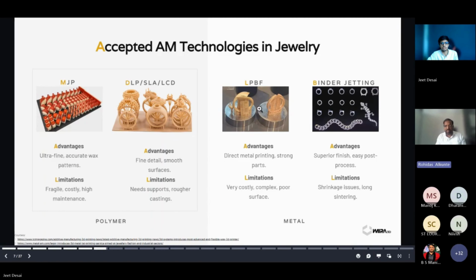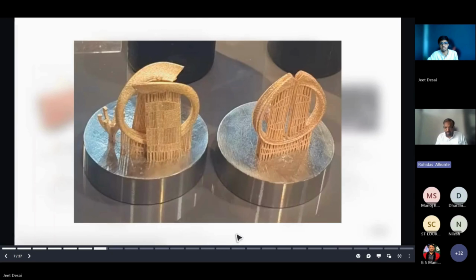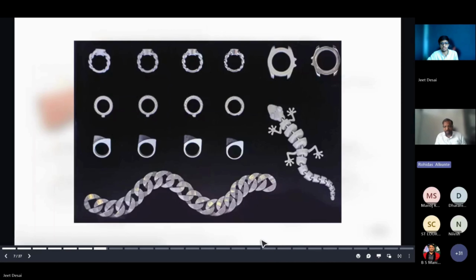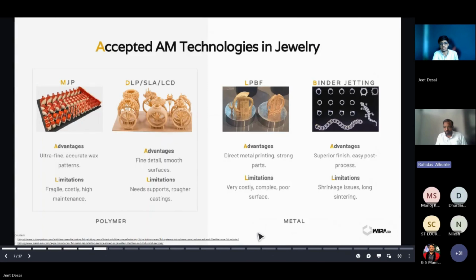And now the industry's approach is to print everything in direct gold. So people are exploring if it is possible to get it 3D printed. Now the challenge is to get a correct surface. If anybody can give this surface at say 2 or 3 micron Ra value, then no one can stop them from being a billionaire in this industry. So this is an opportunity you can think of, and if somebody has a solution, please think of making a machine. In metal printing also there is LPBF and binder jet technology.